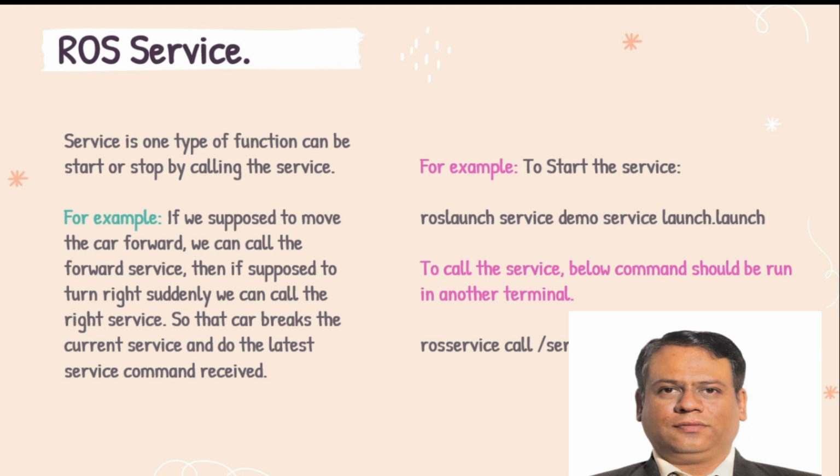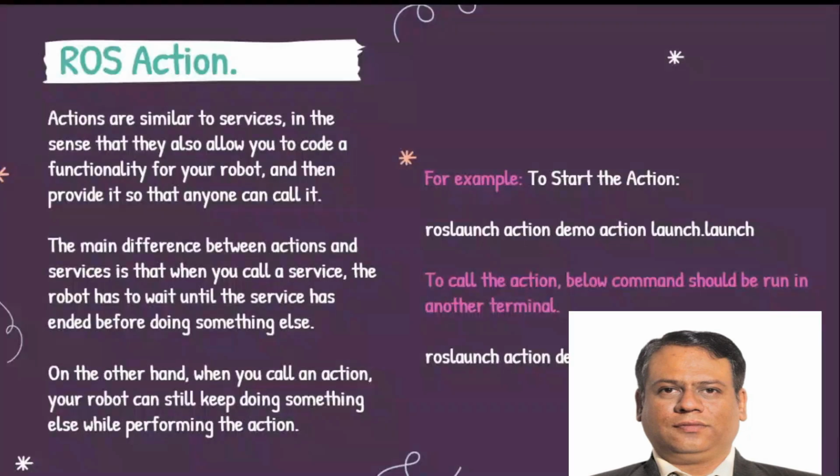Another main thing: if you are going to start the service, you can start it by using roslaunch followed by the service demo. You need to launch the service in the first terminal. And if you want to call a certain function, you can call it with the syntax rosservice call followed by the service. Whether it is going forward, turning left or turning right, those kinds of commands can be sent with the help of ROS service. So that's about the ROS service.